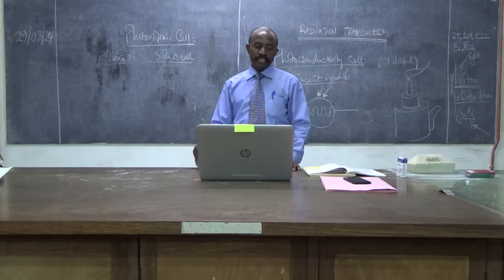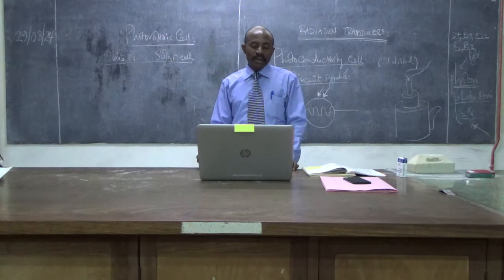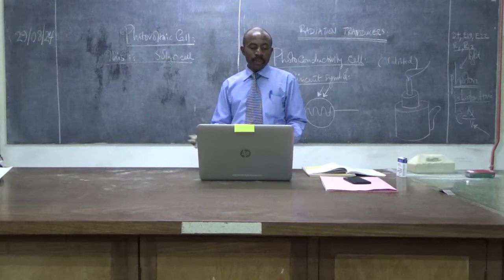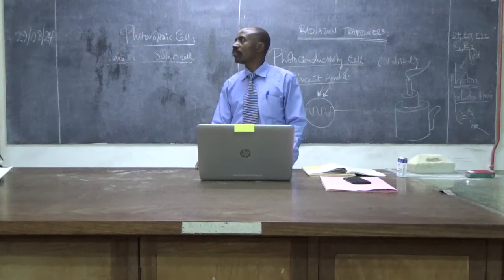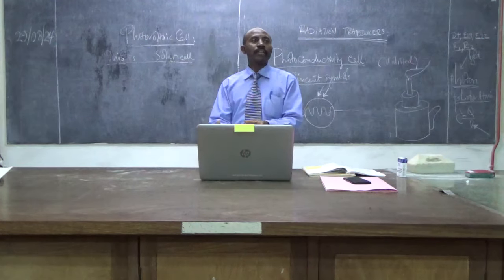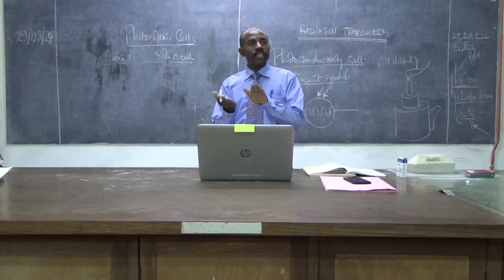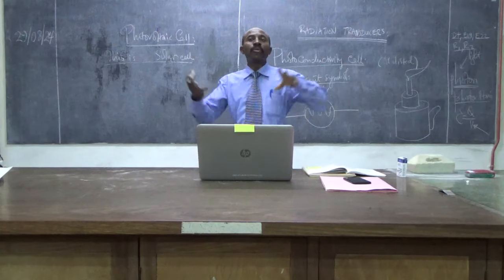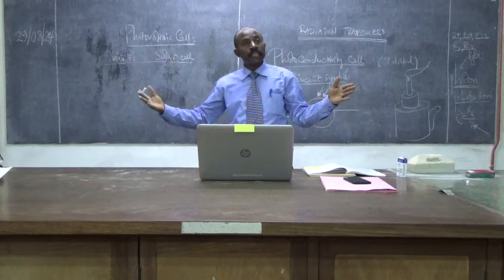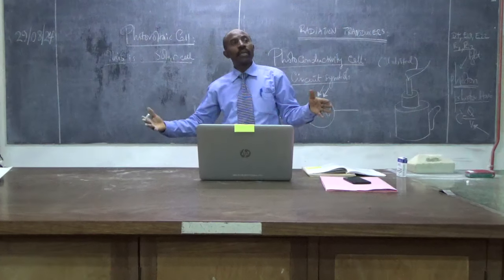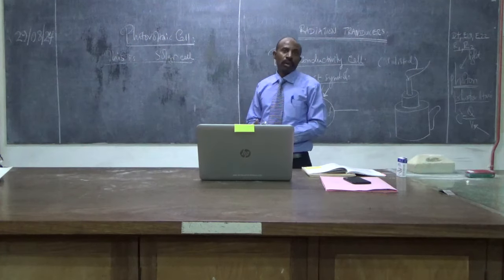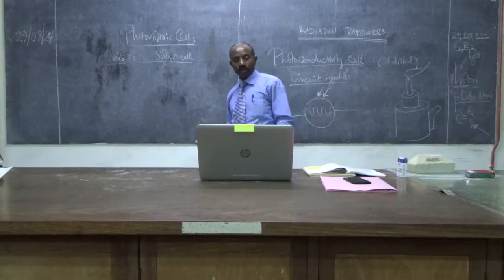And this is simply a diode, which responds to the photons, and then produces the current. And then you can use that current. You can multiply it by putting cells in series, and then produce a significant amount. And it only produces DC, and you can change this DC into AC by using an inverter, and then you use it appropriately for what you want.